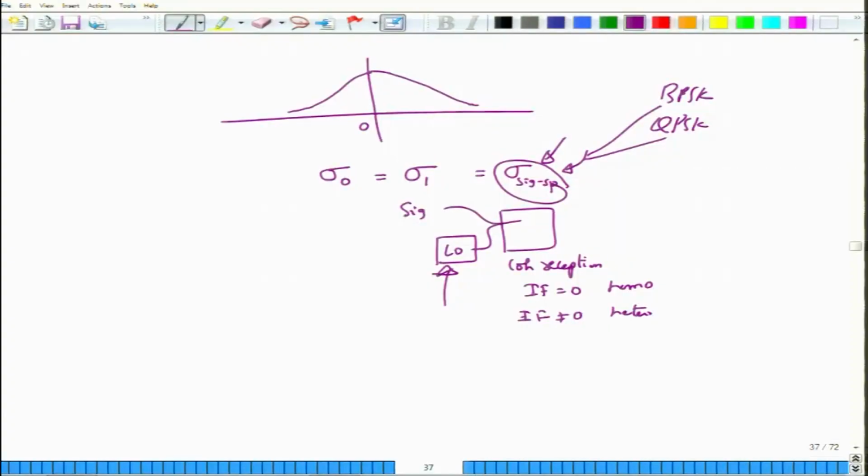So, you can of course eliminate this preamplifier and use an APD, which is an avalanche photodiode, which has a larger sensitivity, but you can obtain the same sensitivity using simple pin photodiodes with an optical preamplifier. So, an optical preamplifier, by raising the gain, will decrease the requirement for the received power and therefore give you more sensitivity.